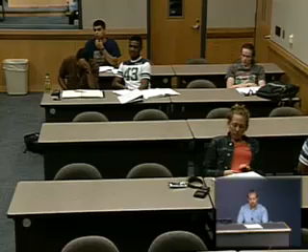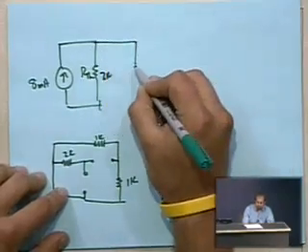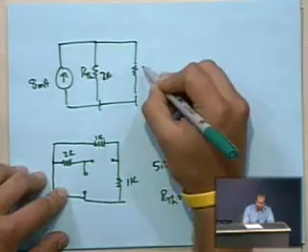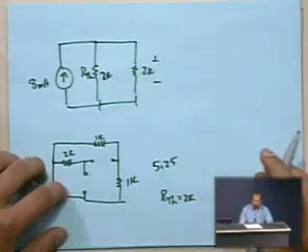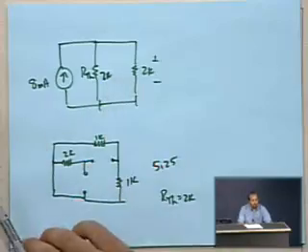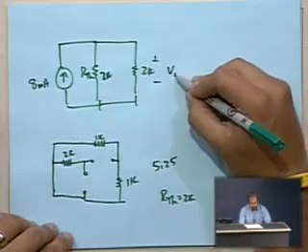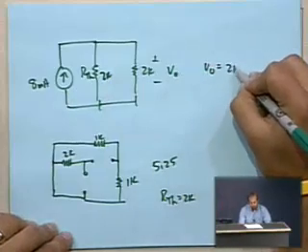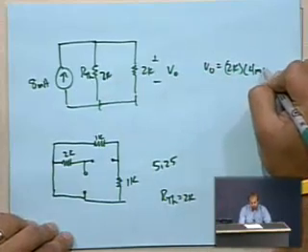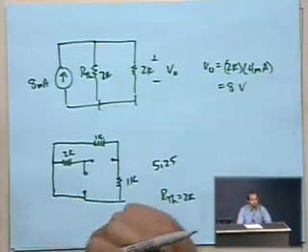So if there's 2K here, and what was the load is another 2K resistor, the 8 milliamps of current will evenly divide across those two. You'll have 4 milliamps running through each of them, and the voltage V0 will equal the 2K of resistance times the 4 milliamps of current, which gives you 8 volts, which apparently is the right answer.